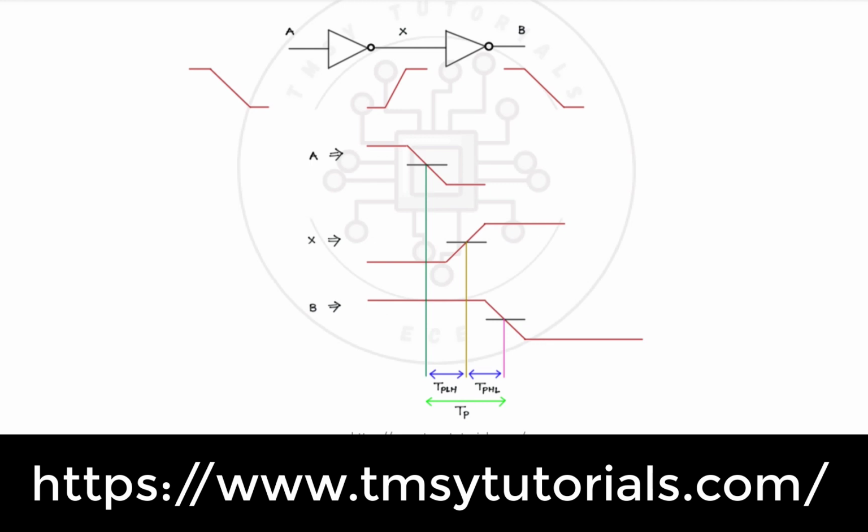I'm taking an input which is coming from high to low, and for the first NOT gate it will get inverted, so it is moving from low to high, and this will be given as input to the second NOT gate. So this X is moving from low to high, so here this will move from high to low.